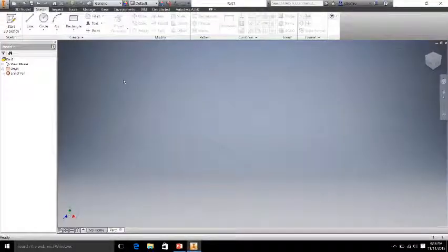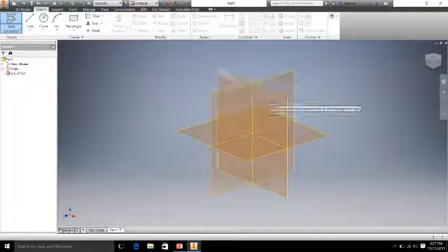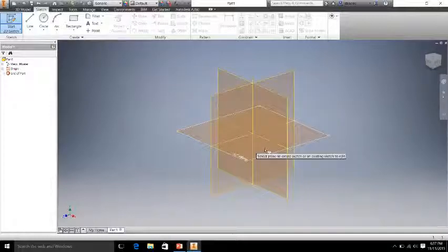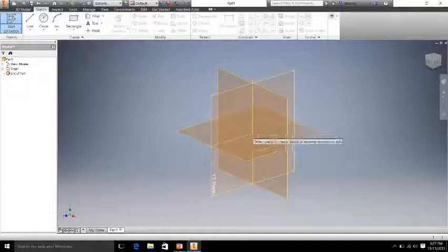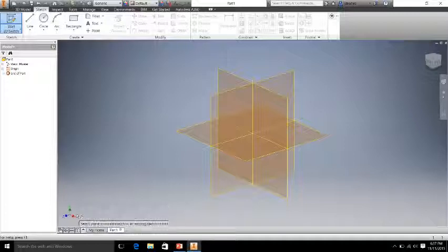But we're going to start sketching this. What we want to do, if you click this top, the only thing you're ever going to use in here is a 2D sketch. If you click the little arrow, you can choose between 2D and 3D. But every time you just click the top portion of that button, it's going to give you a 2D sketch to start out with. Now we see these planes that come up. They're imaginary, so to speak, right now. We haven't drawn anything on them. It's just correlating to this little Cartesian coordinate system down there, but invisible planes.